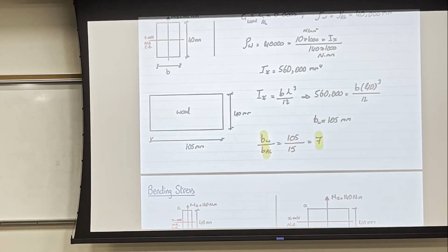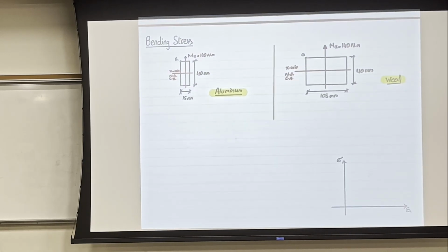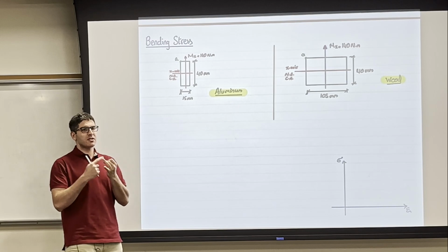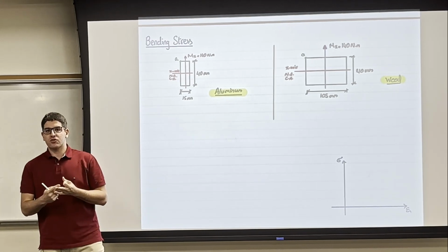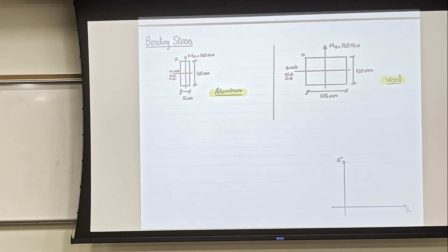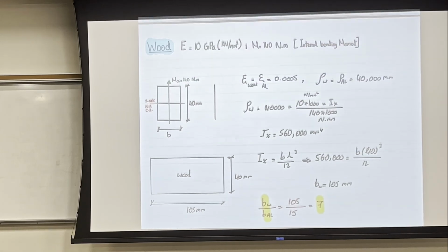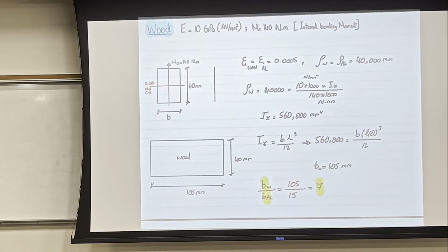Okay, now we came up with a cross section that will have the same radius of curvature, same strain, and same bending strain distribution, because again, I didn't draw this. If I want to draw the epsilon here, we set it at the beginning equal to 0.005, so it's going to be the same as what we had before. So negative, positive 0.005.